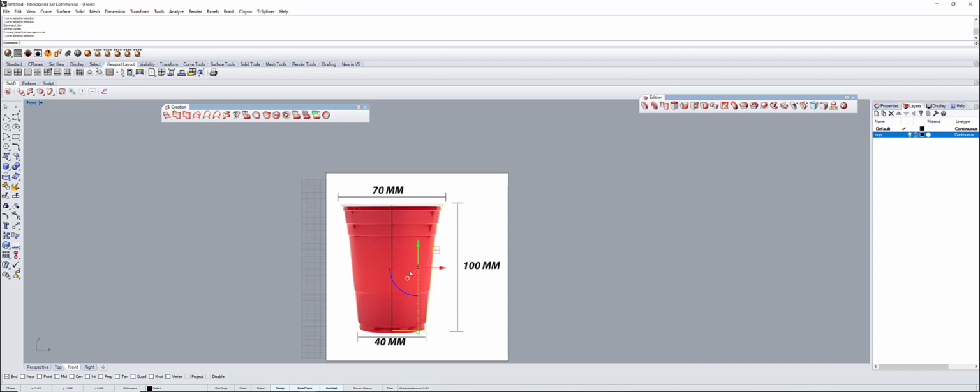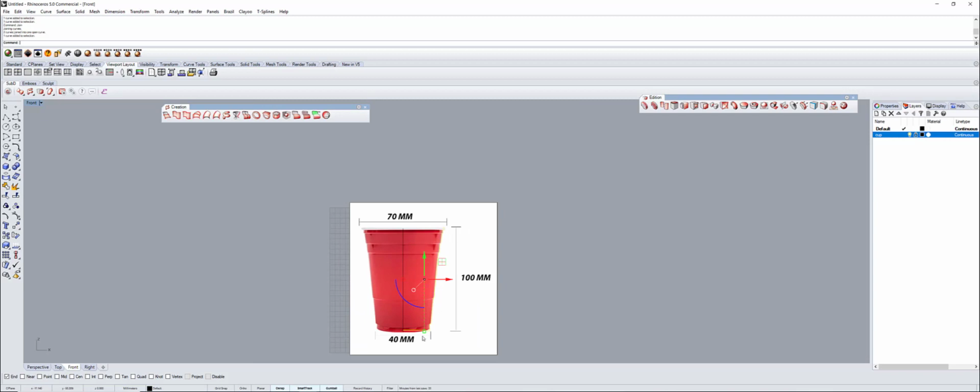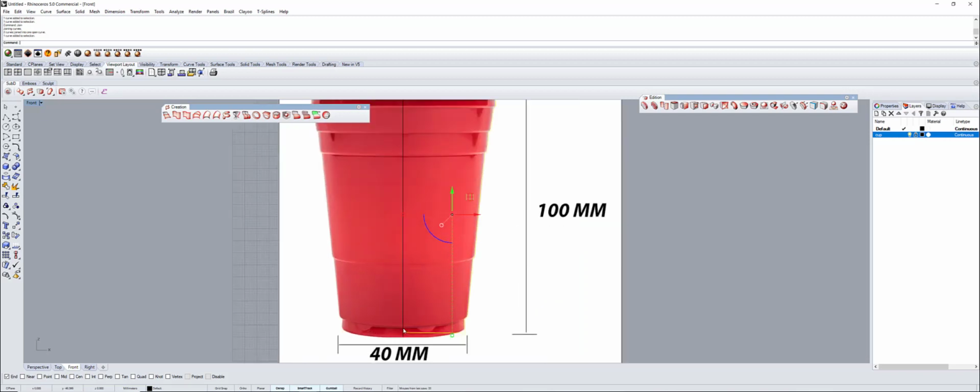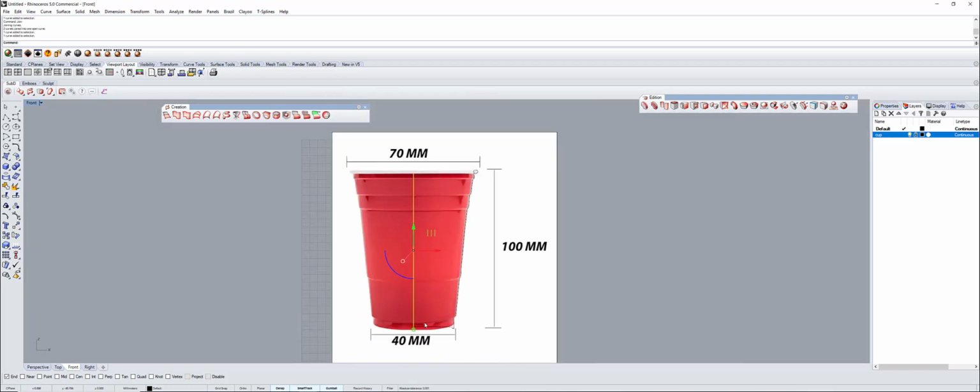So you want to make a wine glass, or for example a bottle of water or a bottle of Coca-Cola, etc. You always have to have your center line and your profile line, your profile curve, because this profile curve is going to rotate using the center line. So never forget that. That's the essential of doing this kind of bottles or glasses or whatever it is.